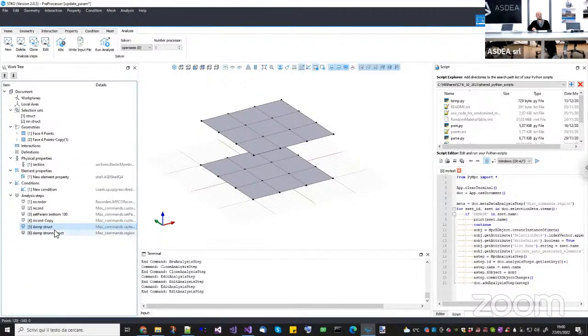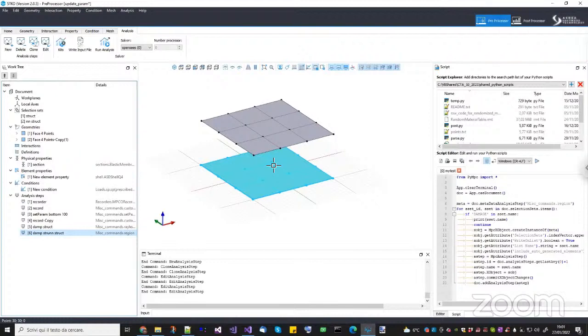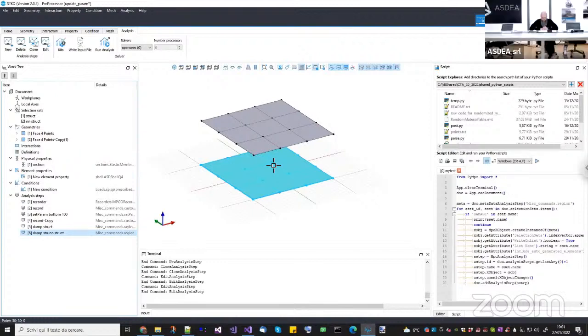You can start by using Rayleigh damping with two different parameters for these two different portions, to take into account that they have very different frequencies. If it works, it's fine. If not, you can write on the forum and try to understand how to use modal damping. Is it fine? Yeah, okay, thank you so much. Thank you.